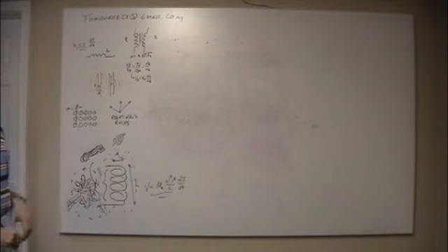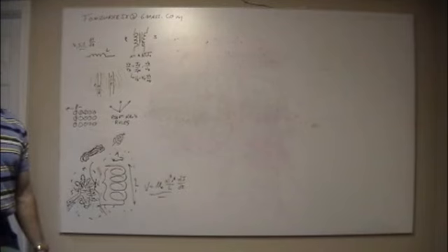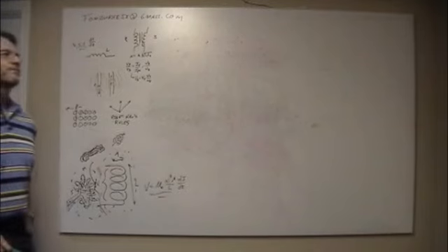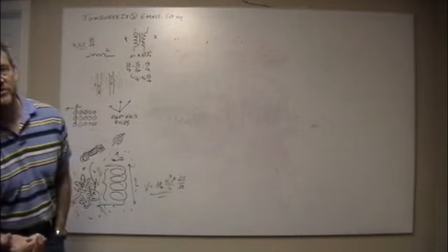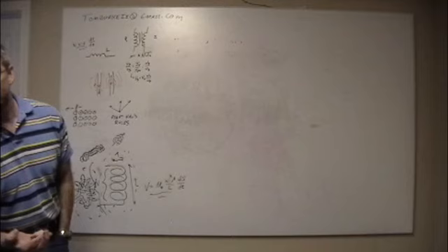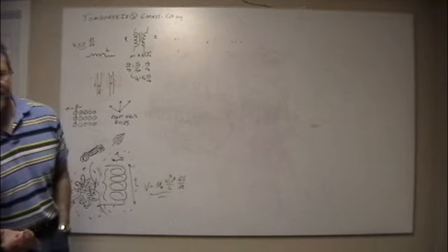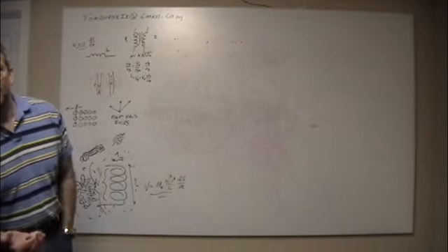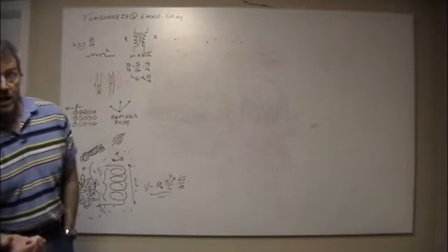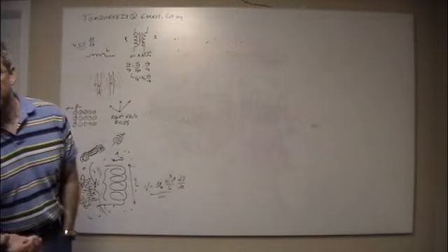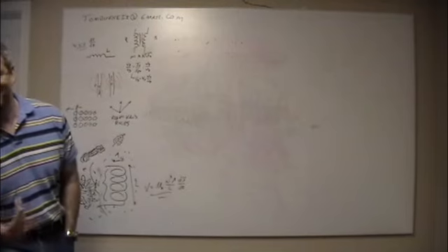What's the shielding for again? Because you have shielded and unshielded? So a twisted pair is going to give you, I think, like 3 dB of noise suppression, 3 decibels, so half power. A good shield can give you up to, I think, 6 dB of noise suppression, or noise immunity.